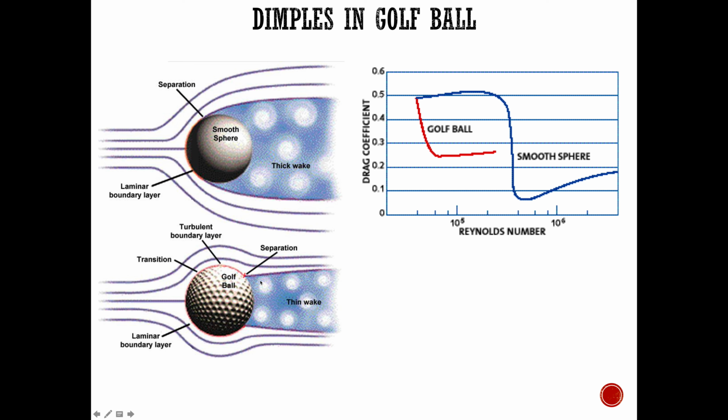I'm not sure if you have looked at it before. There are tiny tabs that pop up on the surface of the wing, right? They create these vortices which energize the boundary layer, which you use to keep the flow attached for much longer. And the benefit of doing that on a wing is that the flow can stay attached at a really high angle of attack. That means that you can take off and land in a much shorter distance, right?